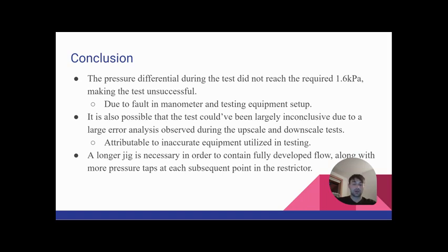And additionally, the test setup itself was actually flawed in the fact that our jig that we attached to the blower motor itself, attaching to the restrictor, was actually most likely not long enough to achieve the fully developed flow to get a more conclusive pressure data from our restrictor taps.